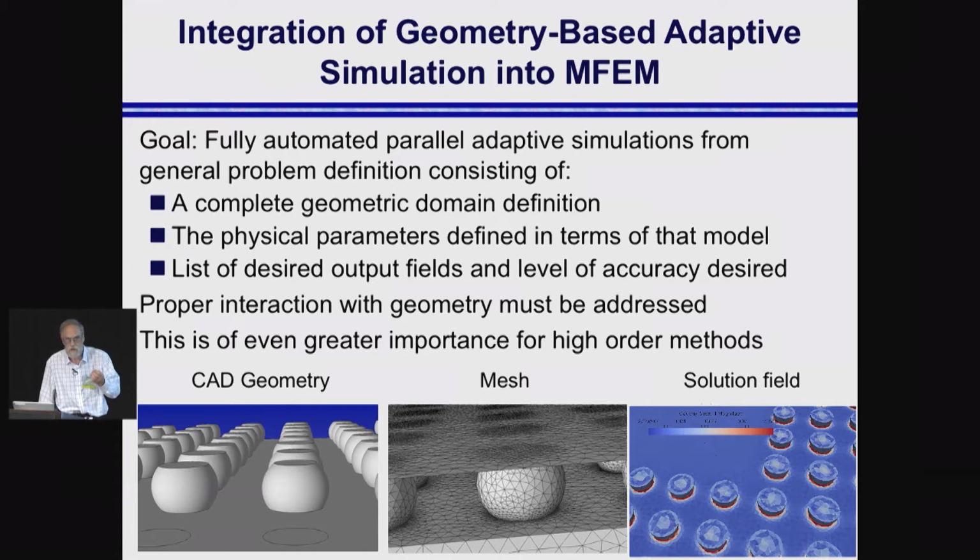By my definition of automated analysis, I'm talking about starting with a CAD model or image data with all the analysis attribute information, the boundary conditions, initial conditions, material properties, and your loadings, defined in terms of that CAD model. No mesh exists. You press the button, and that one I want to be automated from that point on.